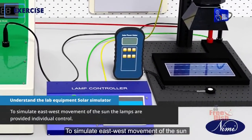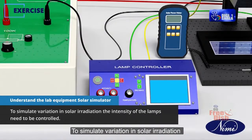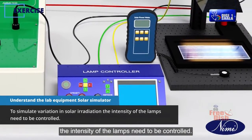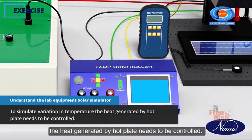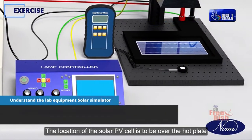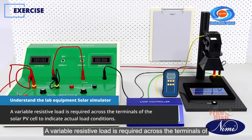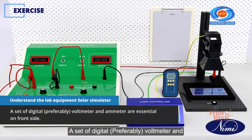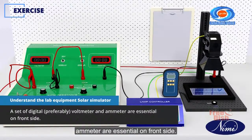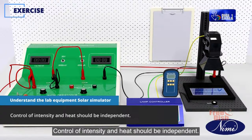To simulate east-west movement of the sun, the lamps are provided with individual control. To simulate variation in solar irradiation, the intensity of the lamps needs to be controlled. To simulate variation in temperature, the heat generated by the hot plate needs to be controlled. The location of the solar PV cell is to be over the hot plate facing the lamps. A variable resistive load is required across the terminals of the solar PV cell to indicate actual load conditions. A set of digital, preferably voltmeter and ammeter, are essential on the front side. Control of intensity and heat should be independent.